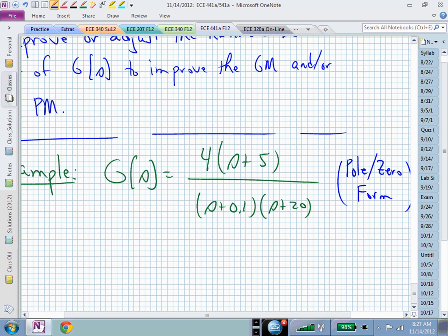And that's nice to have it in that form when we're plotting poles and zeros in the S-plane. For the Bode plot, sometimes it's more convenient to re-express this transfer function such that we normalize all of these constant coefficients to a value of 1. And then all of our action is happening in one location of each factor. We don't have to keep adjusting the gain. We've adjusted the gain once by factoring out all of those pole and zero constant values, and now we don't have to keep adjusting the magnitude of our response. So it might be helpful